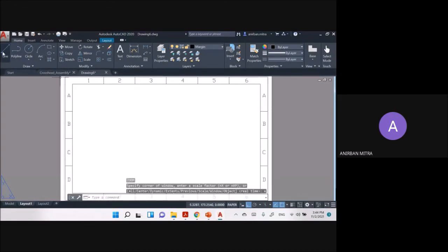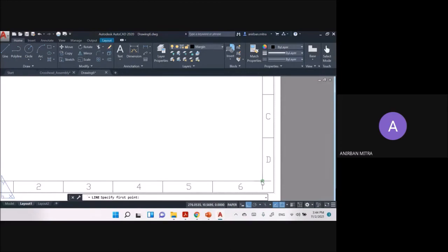The title block can be made using lines, and it's quite obvious really that you need to start from this point maybe. Then write @100 angle of 180. You end up here, go up by 50, angle 270. No, that would be down. So angle would be 90.